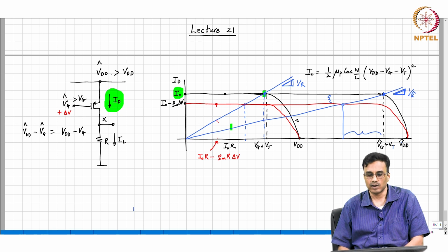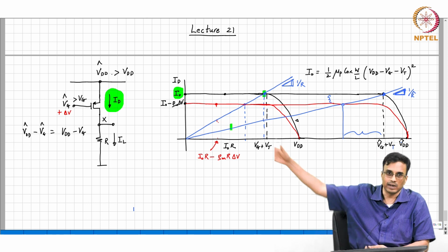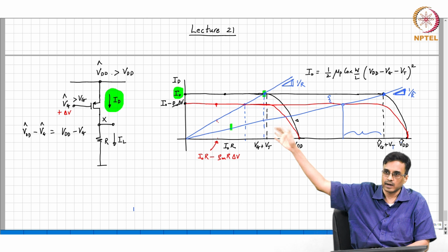If your common source amplifier had a gain of 10 and you wanted to increase it to, say, 100, and if the original supply voltage was 2 volts, you need a 20 volt supply to get an incremental gain of 100 if you use a resistive load. And if I want a gain which is 1000 times larger, this VDD hat will have to go very high.